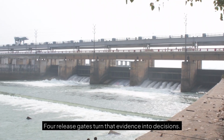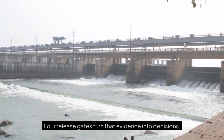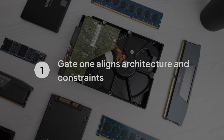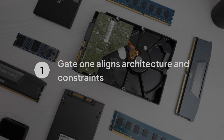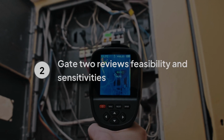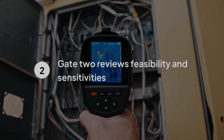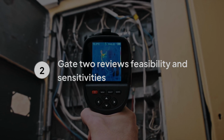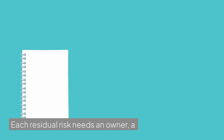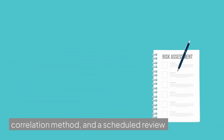For release gates, turn that evidence into decisions. Gate 1 aligns architecture and constraints, recording unresolved information as assumptions. Gate 2 reviews electrical, thermal, mechanical, and manufacturing feasibility together, including sensitivities to stack-up, placement, geometry, tolerances, and cooling. Each residual risk needs an owner, a correlation method, and a scheduled review point.